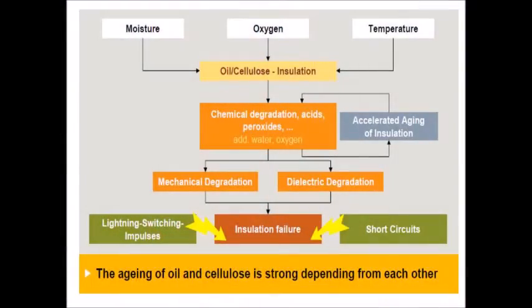And by the way, besides partial discharge, once the arcing occurs, the cellulose actually will be broken down, and this creates a whole bunch of different gases. The industry is very fond of using dissolved gas analysis, which is by sampling the oil, looking at the content, and finding out analytically how many species are present.